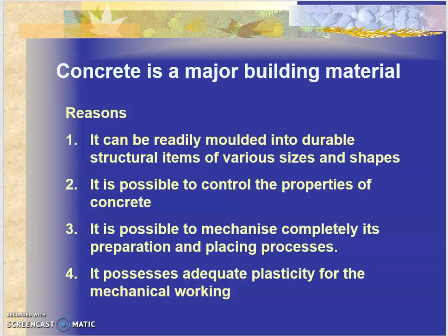So whichever part of the structural member is made out of concrete, let's say you're pouring concrete in a beam, the lower part of the beam will be under tension. In that case, we reinforce it with a material which will be good in tension. Right? So, you will see steel bars in the lower part of the beam. You do see them on top also because you need to provide nominal reinforcement on the top also. There are IS codes which tell us how exactly detailing is to be done. That we will know in depth in the fifth semester.